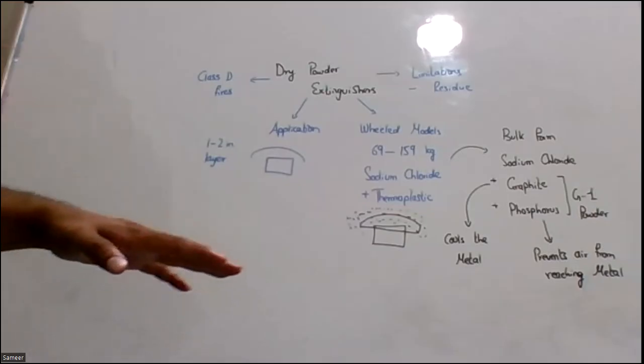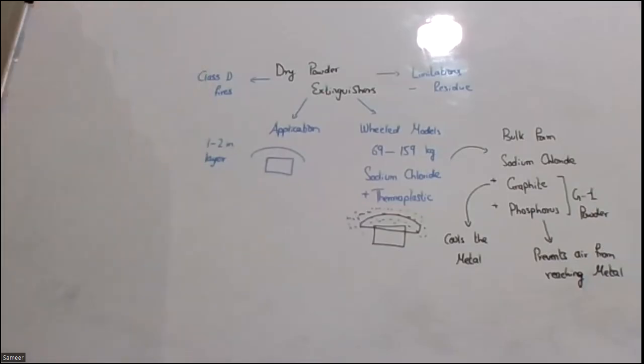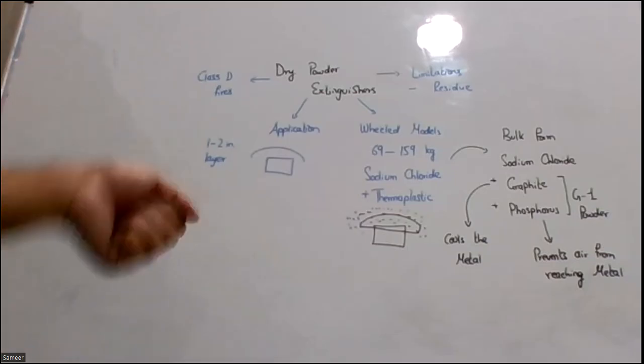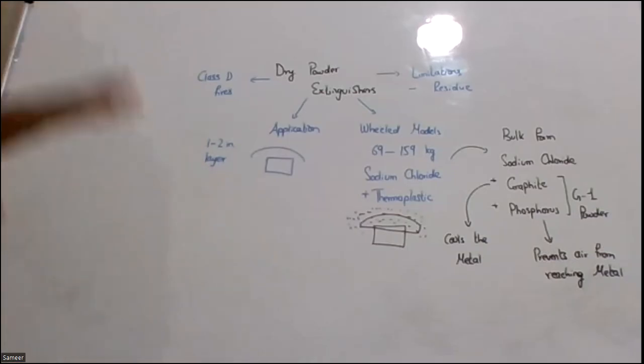The hard crust that forms is not applicable for ABC fires. It requires a higher temperature to form the hard crust, and the crust may not form if the temperature is lower. So we use it on metal fires. When the crust is broken down, we can clean it out, and the metal will be again in the form that is required for us. So we can use it very effectively there.